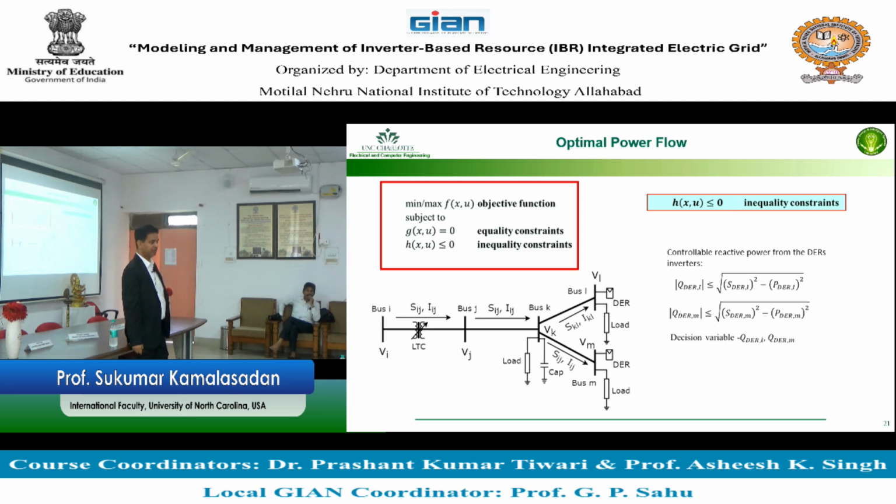So what we did in a field in US, we had a battery with 250 kW with 750 kWh, a 3-hour duration battery, 250 kW. You put a 1 MVA inverter. 750 kWh is a maximum thing, so 1 MVA. So you oversize the inverter, so you get extra, square root of whatever the algebraic addition, but you get roughly 30% of the reactive power extra from the inverter sitting at that point, and then you can manage that voltage at that point.